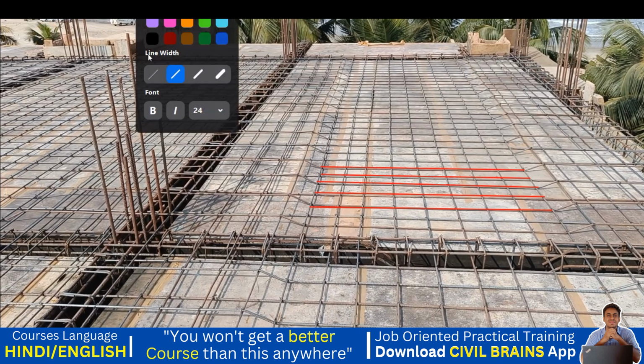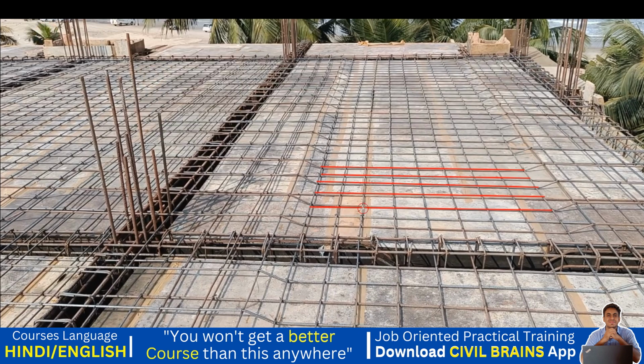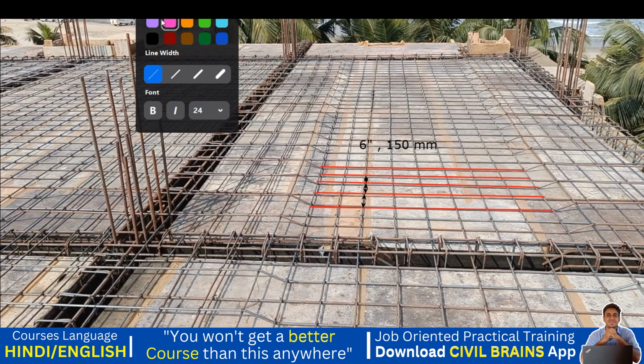See, few things will take you time. If you are a new learner, it will take some time, but it is a very good way that you are learning, okay. So this was the spacing, how much? I'll write it here quickly. It was a 6-inch spacing. 6 inches means it comes out to be 150 mm center to center spacing in the center. But the same thing, can you observe it at the sides? In the sides I'll do it in this way.